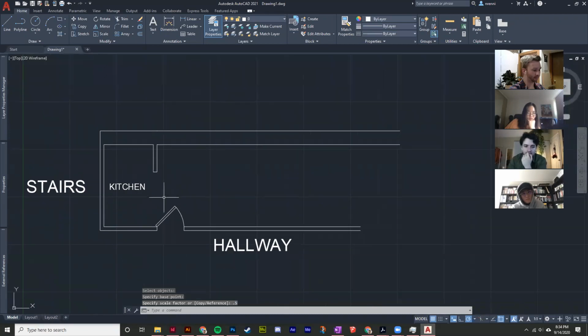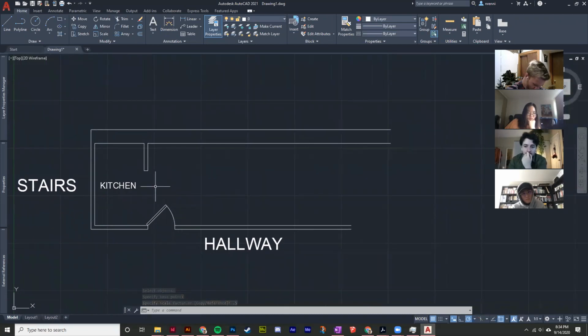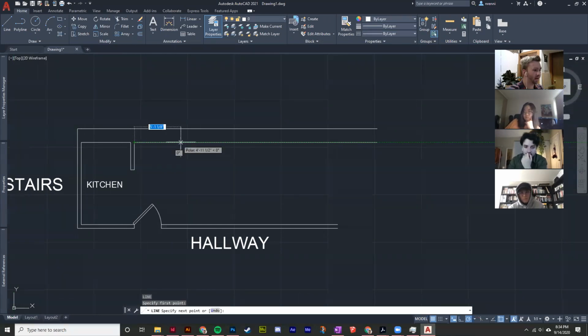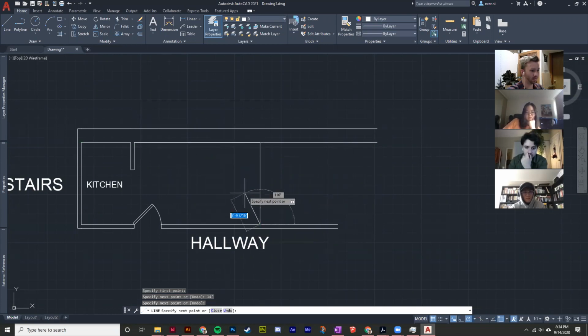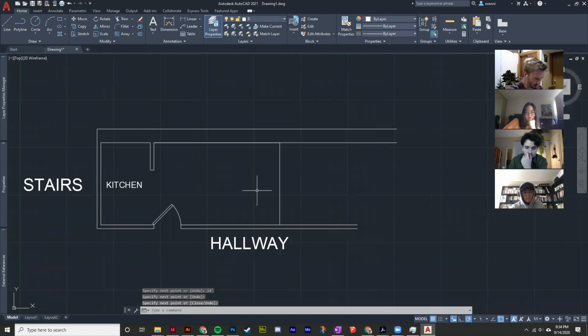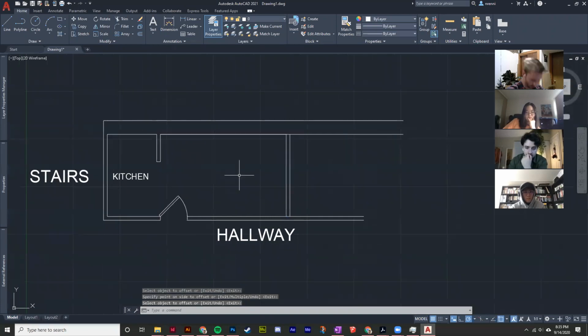by half. Okay, so the next thing I'm drawing is the wall between my main space and my bathroom, which I have as 14 feet from my wing wall. So I'm going to start a line, click on this corner right here, and then do 14, I'm typing 14 feet, and then that made this line right here, and then I'll go down like that. So, and this is my bathroom. wall is interior, so I'll do 5 inches offset. There is my bathroom wall.